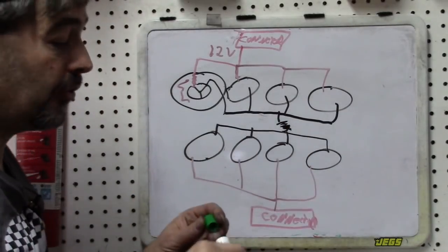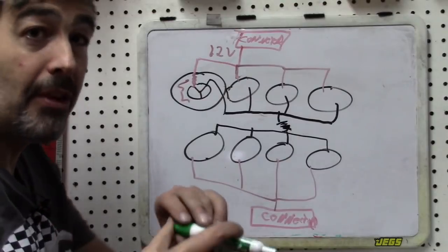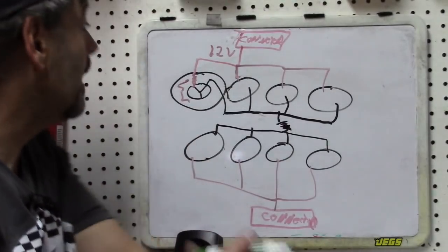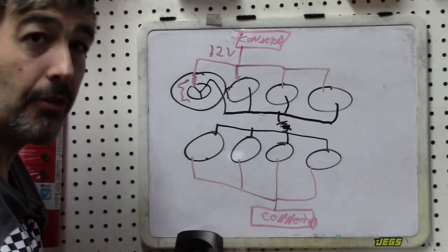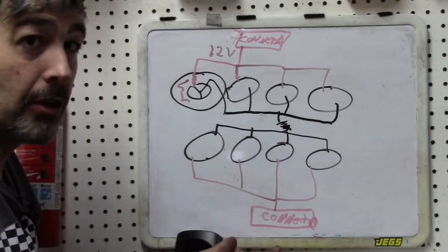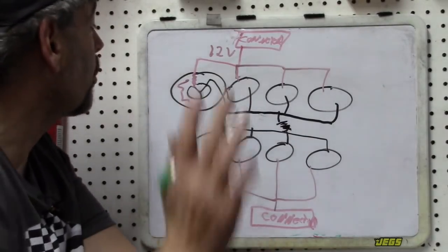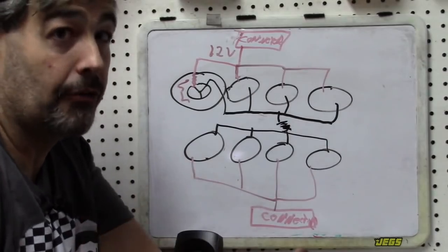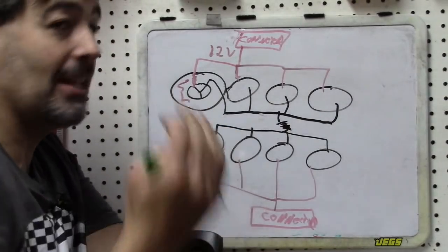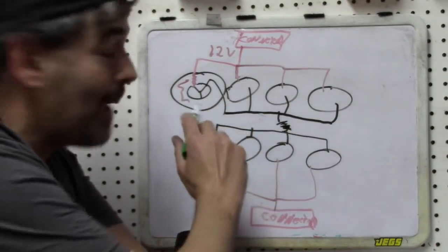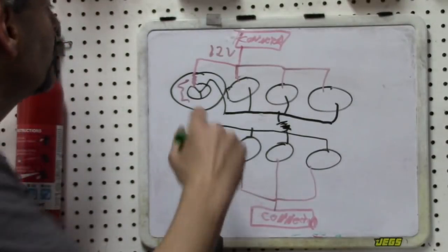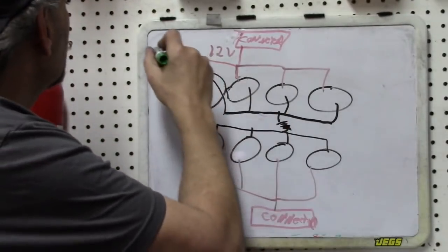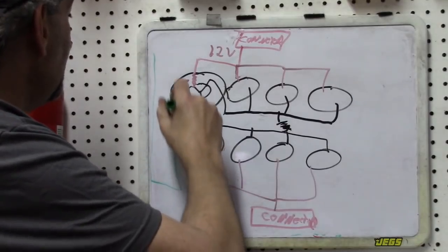All right, now that of course leaves us with the control, and this would be your 3-wire design. So again, like I said, if you understand the 4-wire, by default you have to understand the 3-wire. So we're going to complete the 3-wire design, which you guys are already familiar with. And that's going to be independent control of the base on the NPN transistor by the PCM. So let's put the PCM over here.